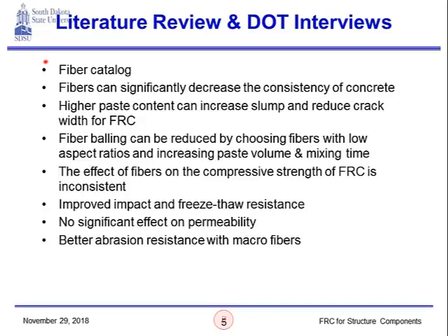Now, going to the findings from looking at the previous studies and DOT interviews, fibers can significantly decrease the consistency of concrete. This is something that we should always keep in mind, as the workability of concrete really drops very low. And this is something that we also noticed in our experiments. Whenever we design fiber reinforced concrete, we expect the slump to drop as we add fibers, and so we should account for this by adjusting either the water to cement ratio or the water reducer and superplasticizers.